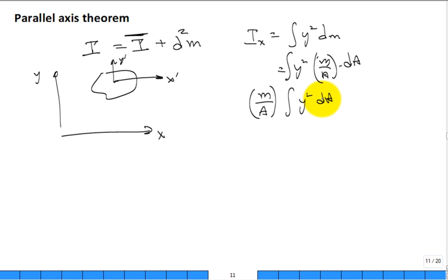Hey, we've seen that before. And we think about, okay, I'm going to describe the location of this point. If I describe the location of that point in the original coordinate system, that's not a centroidal coordinate system, then I can also describe it by the addition of this vector, which gives me the location of the centroid of that coordinate system, and then the location of that point with reference to the centroidal location. So either way you look at it, you have r is equal to r sub c plus this r prime.